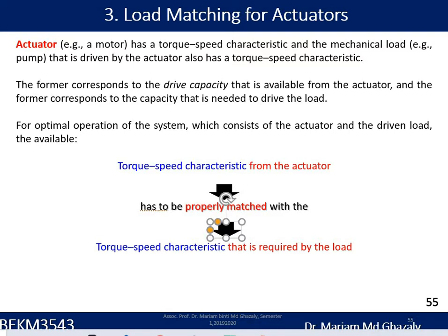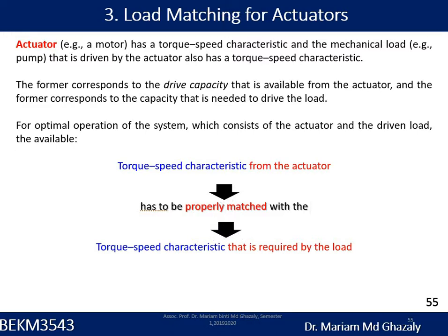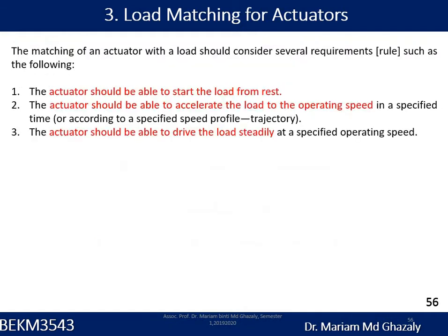Okay, so for the optimal operation of the system, we need to make sure that the torque speed characteristics of the actuator is properly matched with the torque speed characteristics required by the load. The matching of an actuator with a load should consider, firstly, that the actuator or the motor itself should be able to start the load from rest.